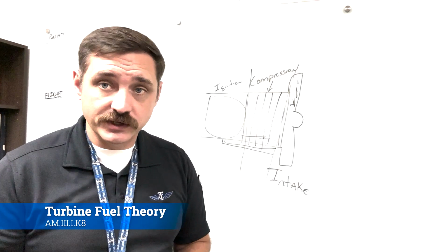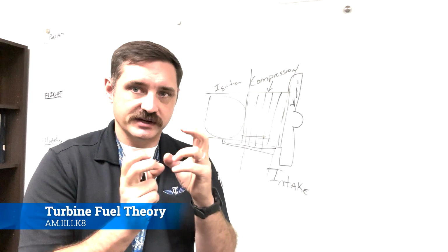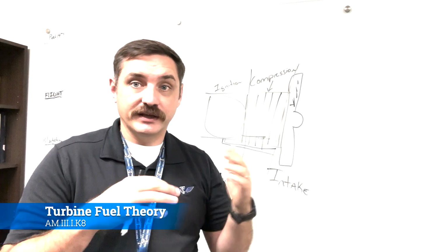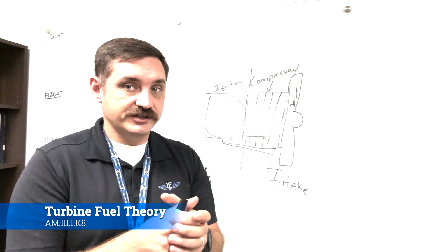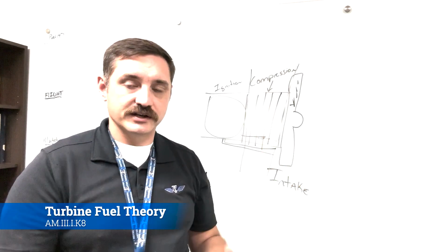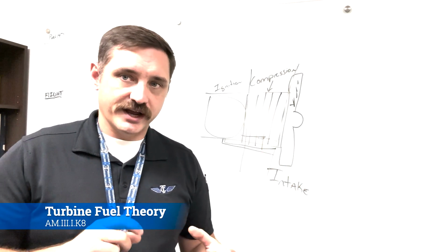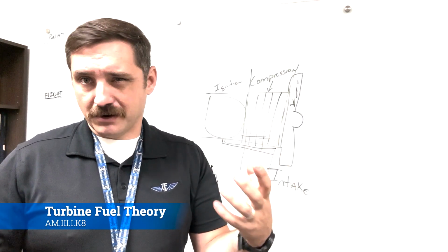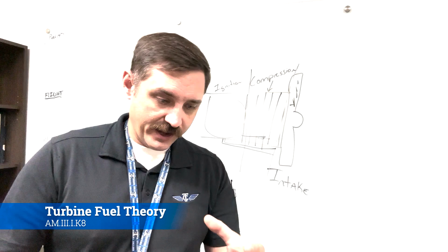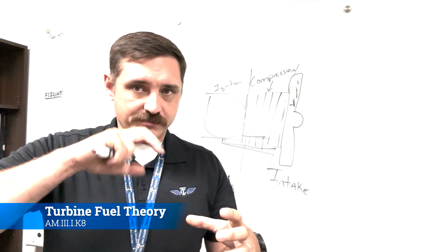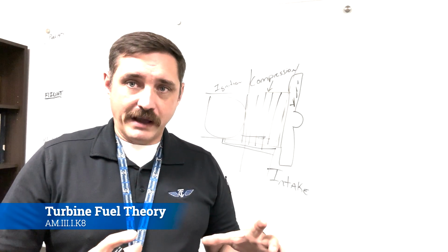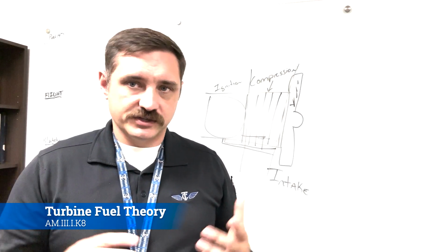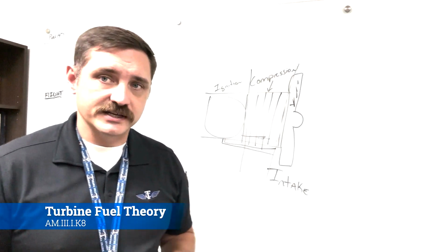Now, it's different than a fuel injector, whereas a fuel injector is right there next to the spark plug and is going to try to help ignition. The spray nozzle literally just sprays fuel in a big pattern. So you'll do a fuel nozzle check where we run fuel through the engine and you hold a Gatorade bottle or whatever we used to use, anything that would catch that fuel, and you're making sure that the spray nozzle comes out in a uniform pattern and it's not all wonky or weird, which would indicate that the spray nozzle is somehow damaged or clogged. You need to fix it.